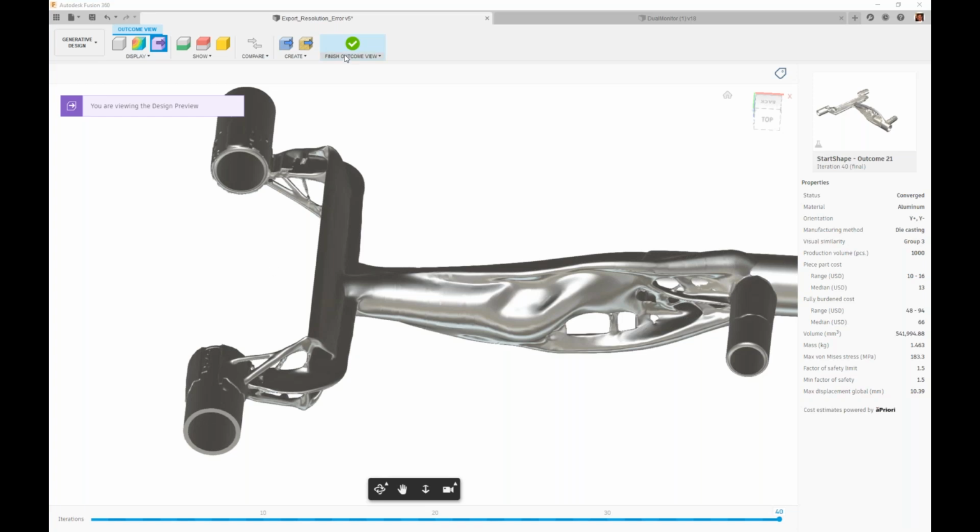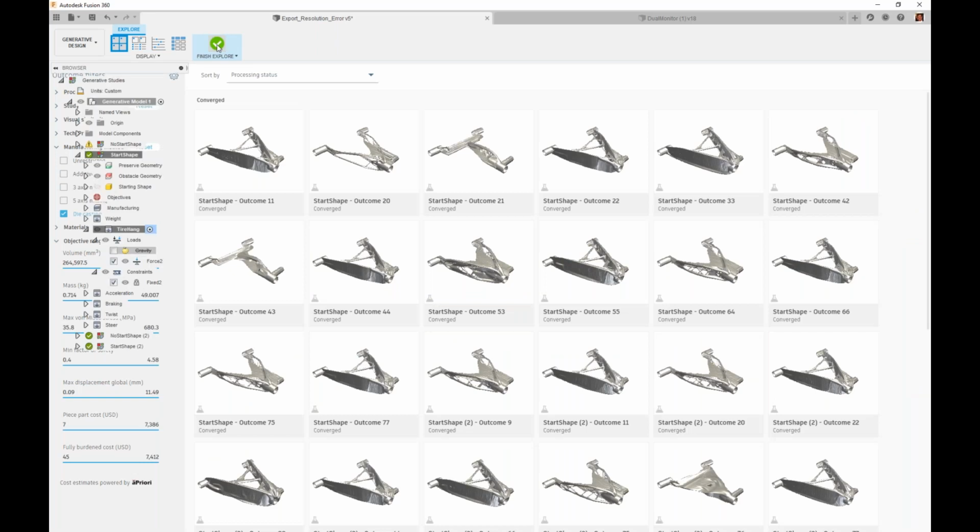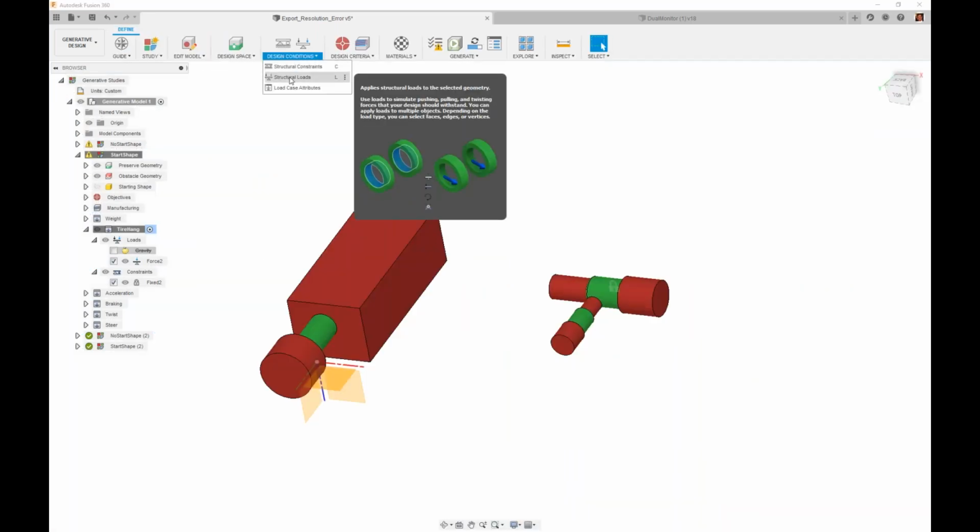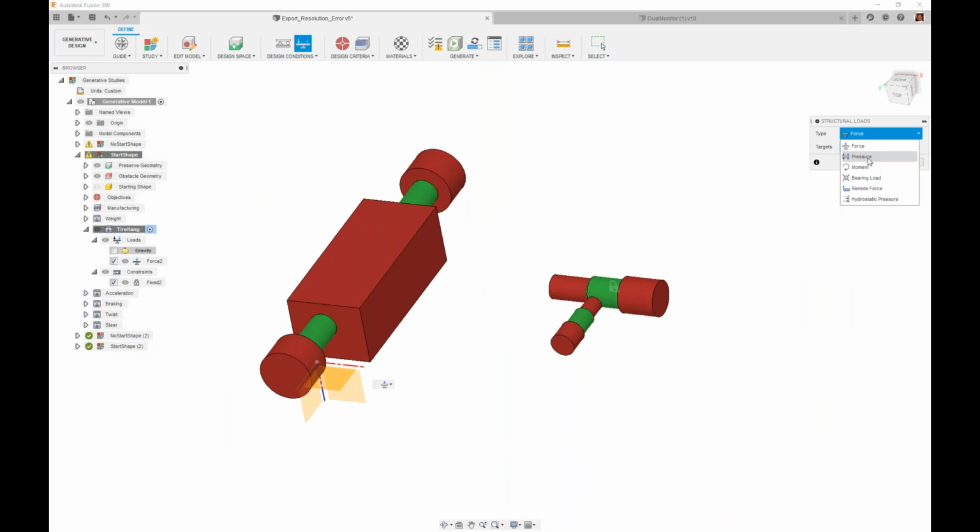In that case, it'd be a matter of assigning appropriate loads and constraints. You could assign hydrostatic pressures or pressures to represent the different forces acting on those impeller blades and where they are. Then we would produce outputs for what the interior structure of that impeller might need to be to withstand those.